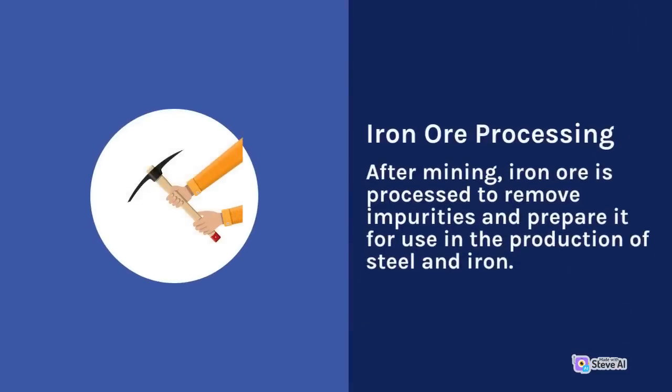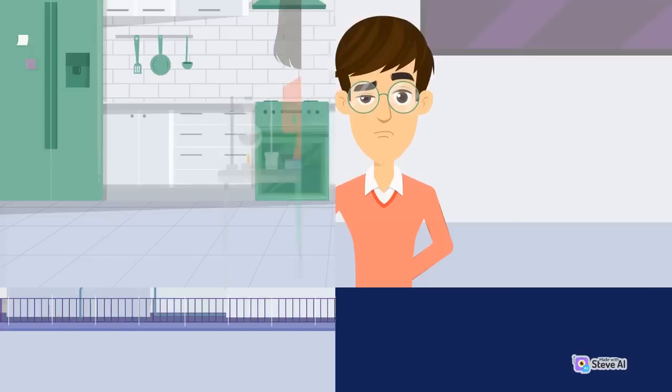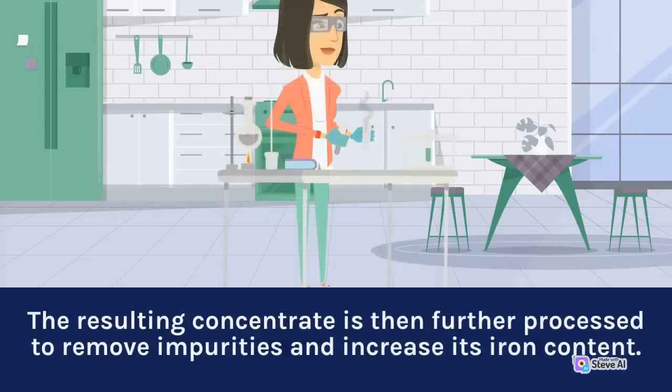Iron ore processing. After mining, iron ore is processed to remove impurities and prepare it for use in the production of steel and iron. Processing involves crushing the ore to a fine powder, followed by separation using magnetic or gravity methods. The resulting concentrate is then further processed to remove impurities and increase its iron content.